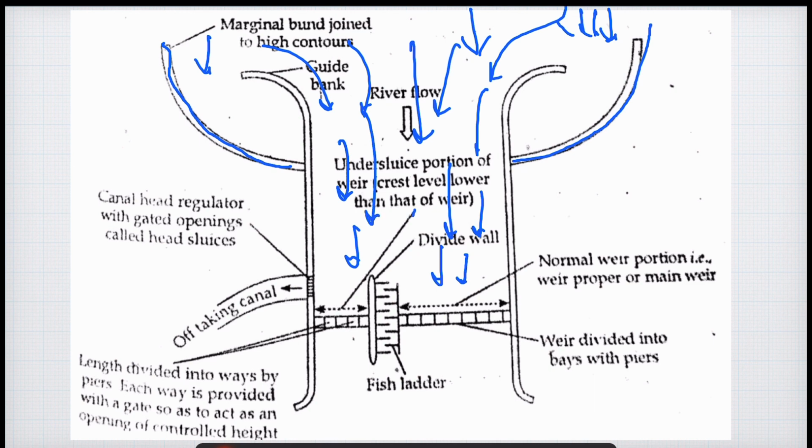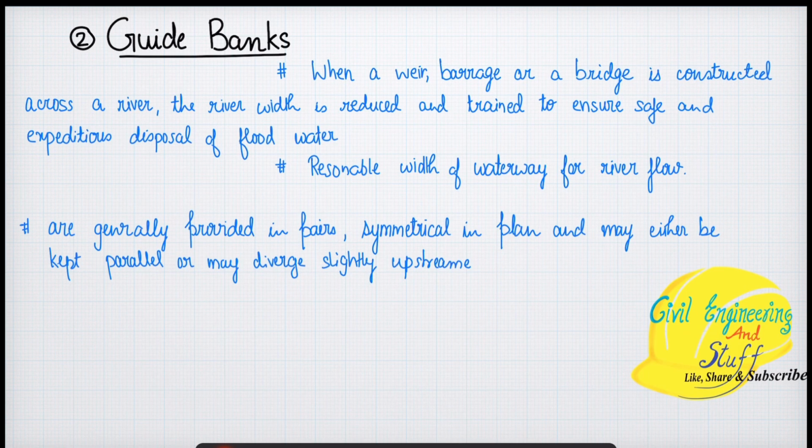Okay, so for that, what we use is what we call the guide bank. These are the guide banks. These are used to confine the flow of the water to ensure safe and proper disposal of flood water. It has a reasonable width to ensure that the water flows.